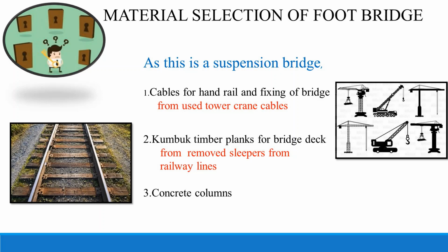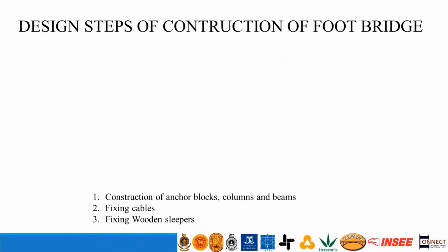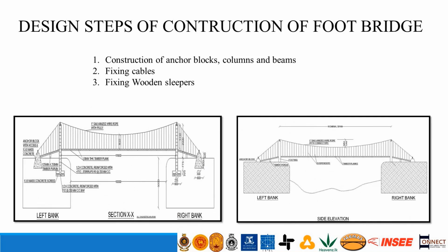Then I'll explain how we did our design of the footbridge. First step is construction of anchor blocks, columns and beams. Then fixing cables. Finally, fixing wooden sleepers.